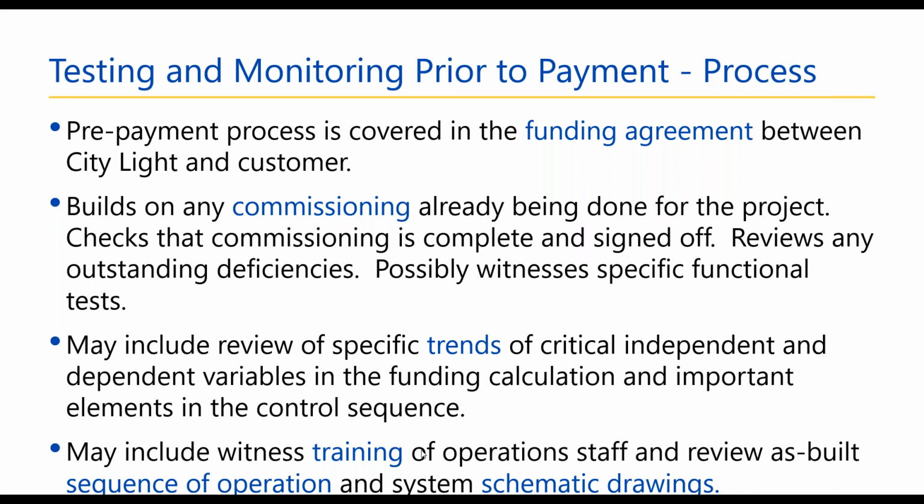One is that regardless of your role in a contract, you really want to enforce and post on the mechanical room wall both the schematic drawings and the sequence of operations in any construction project, because the data means nothing unless there's an expert around who knows what it means. And someone on site needs to know how the system's supposed to work.